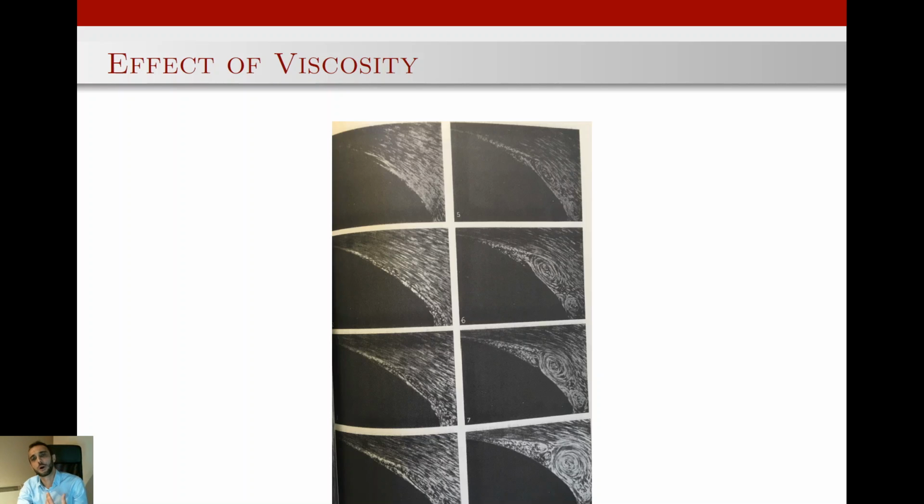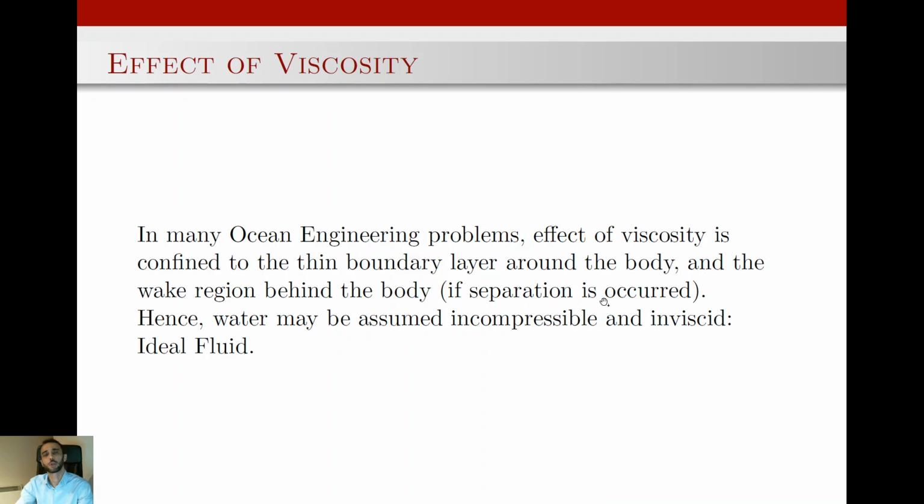Now, all these effects are related or are due to the viscous effects on the fluid. So if we could assume that outside of this region, viscosity does not play a role for us, which is actually a typical case for most of the ocean engineering problems, the type of problem that I mentioned earlier, then we can assume that the fluid is inviscid.